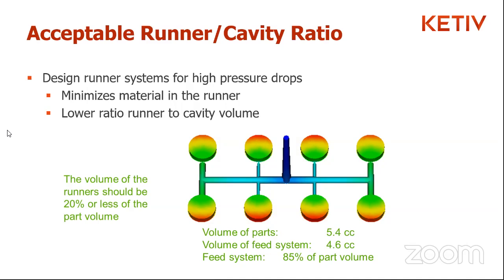Now, similarly, all of this relates to runner balancing. So if you're looking at multiple identical parts, designing them all at once, then absolutely you do need to consider all of these different factors. And in any case, it's definitely good to have this information about fill time and flow rates. Just because you're molding one single part doesn't mean, for example, that you should ignore the frozen layer ratio, etc. Yeah, and we'll touch on that next session.